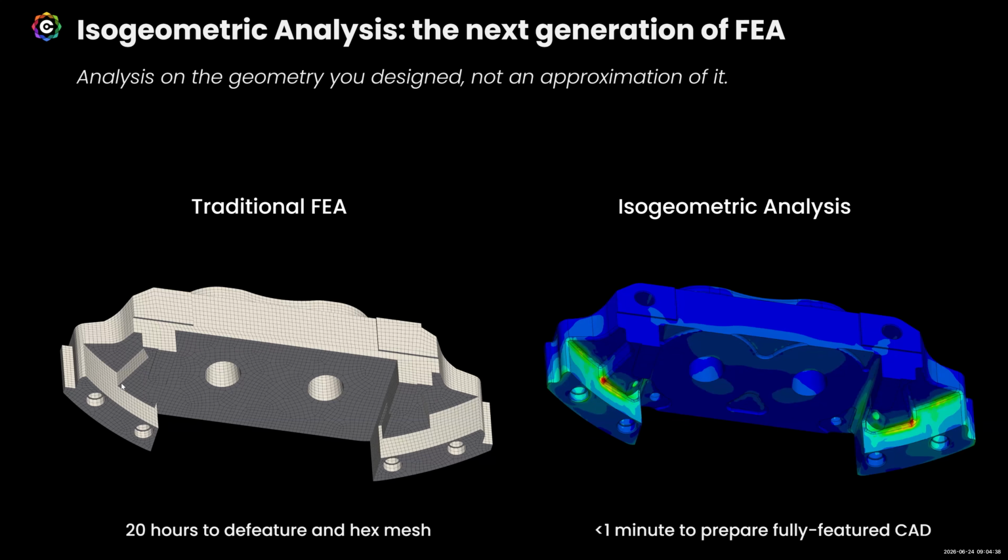And what that ends up doing from a traditional FEA standpoint is that after my analysis, after my simulation, I pull out Shigley or Roark and look at my stress concentration factors. I've got all of these different fillets I removed. What do I think the max stress is in these fillets? When you can just run directly on the CAD geometry, that level of approximation is gone. I just know what my simulation predicts for my stress concentration on those features. So less time and more accurate.